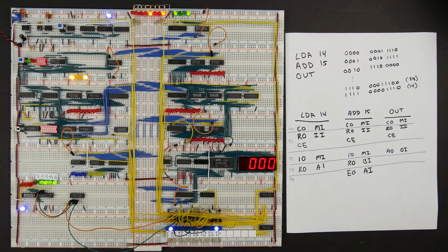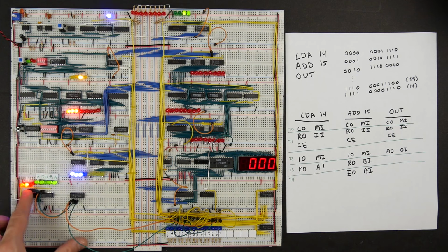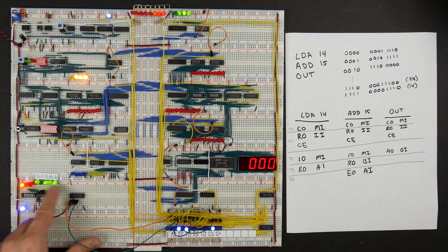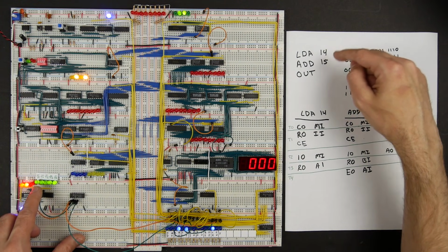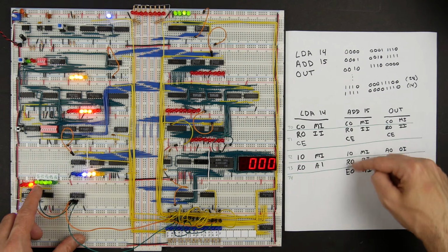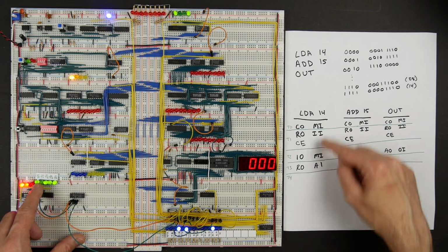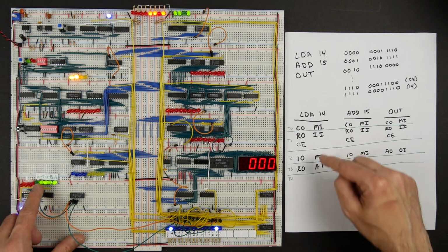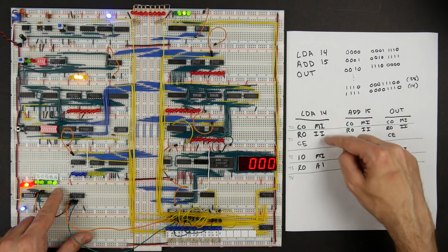In the previous video, we started building the control logic for our computer, and we started by building a counter that counts through each step of our instruction cycle. Because each instruction that we want to define for our computer, whether it's load A, add, output, each of those instructions is made up of up to 5, or really it's always 5, although sometimes the last steps don't do anything, but it's 5 different microinstructions. And this counter counts through from 0 to 4 to keep track of which step we're on.